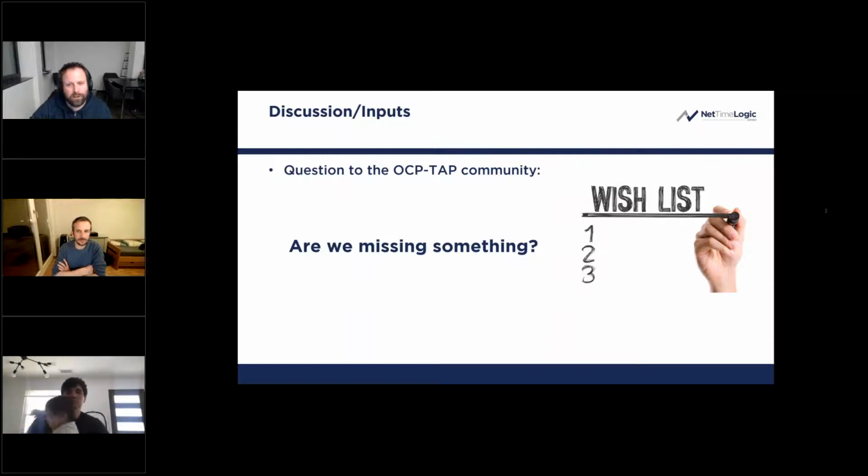But do you really want to do that directly on the time card? You anyhow have a much more powerful host, especially with more storage, if you're talking about long-term statistics. No, I agree with you, on the PCIe host side. But just as an option, for an application where you prefer things to run regardless of the x86 platform restarting, or whatever is going on with x86. So you have higher reliability with this microprocessor running more deterministically. There's no OS, it's bare metal, and then you know what's happening.